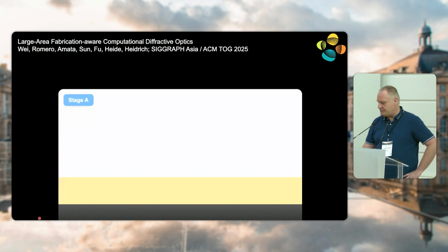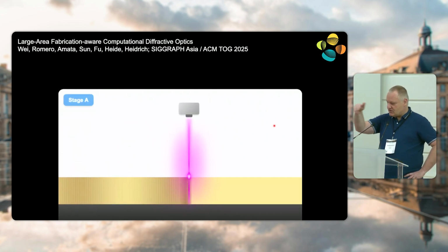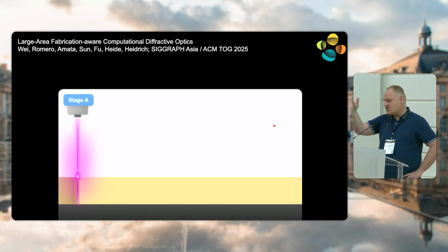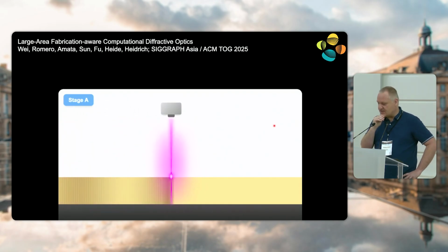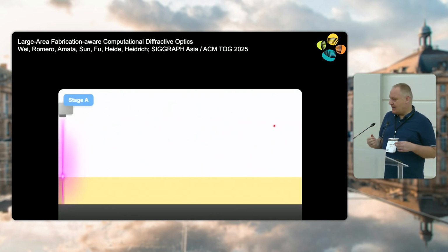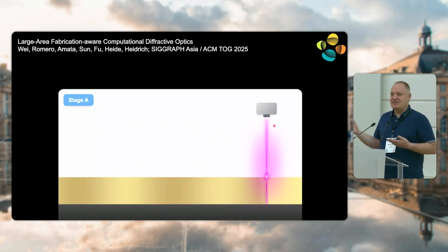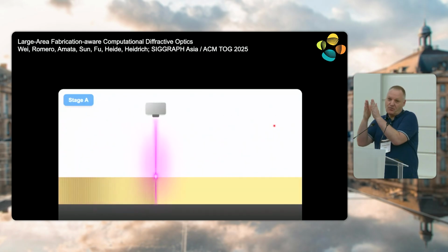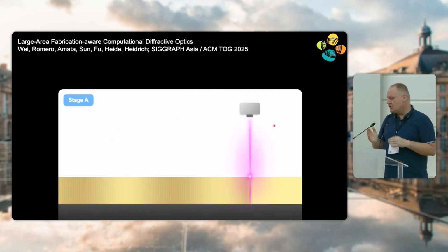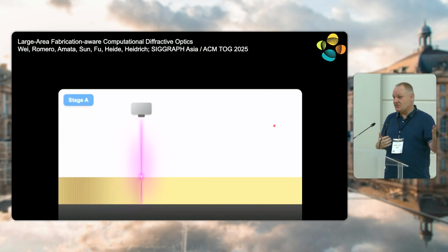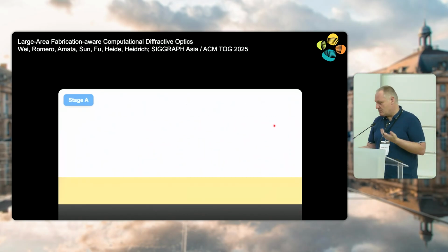You have a glass substrate down here, and then you have what's called a photoresist. The direct laser writing part is that you have a laser beam scanning across the surface and depositing a gray level exposure dose onto the photoresist. The first thing you get is that this laser, at the scales that we want to fabricate, and we're always right up to the physical limits of what the device can do with these nanofabrication techniques, introduces a blur, because of the diffraction limit of the laser.